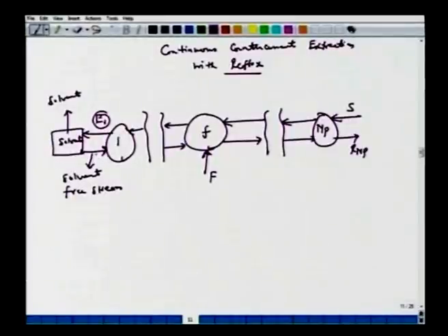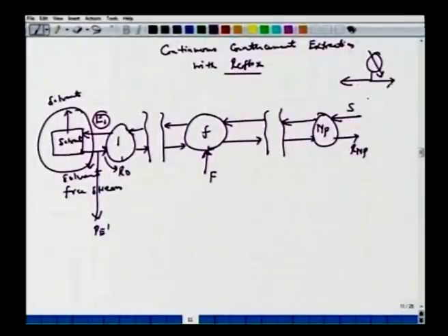So you have a certain amount of reflux. You can withdraw the product, let's say P, and you can have this raffinate as R0, the reflux, which goes back in this direction. This is a situation very similar to the distillation column, where we had the condenser, and at the top of the column we had the reflux going back. In this case also, with the solvent which comes here, we have a solvent separator. You recover the solvent, and the solvent-free stream is sent back to the first column.